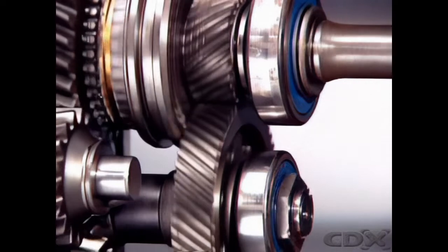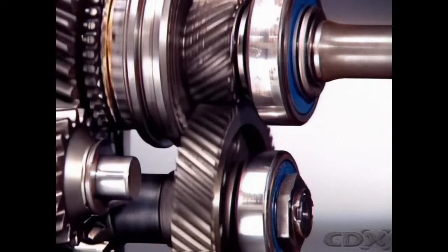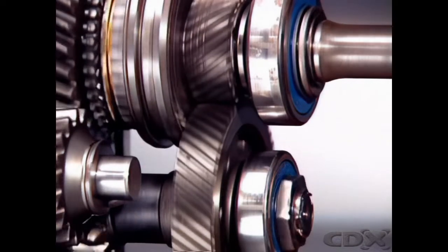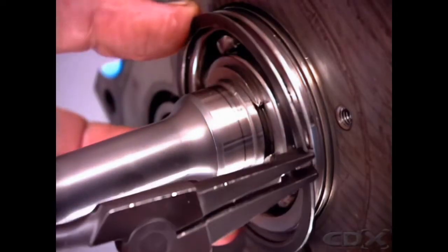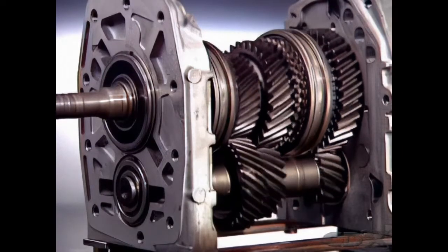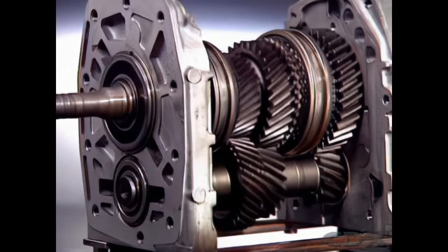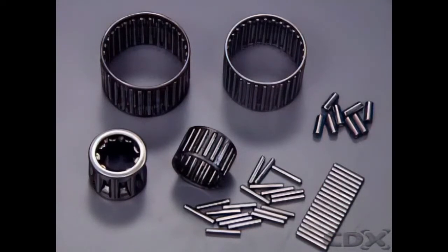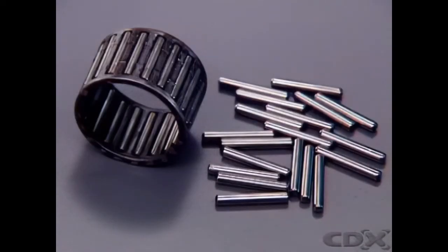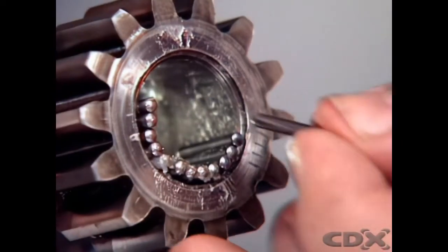The helical gearing creates radial and thrust loads as the gears try to force each other apart and move endwise. A circlip in a groove on the outside of the bearing can locate each shaft in the casing and maintain the alignment of the gears and engagement hubs. Roller bearings are common where loads are purely radial. Needle roller bearings can be caged or as a loose number, assembled to operate directly on a hardened gear or shaft.